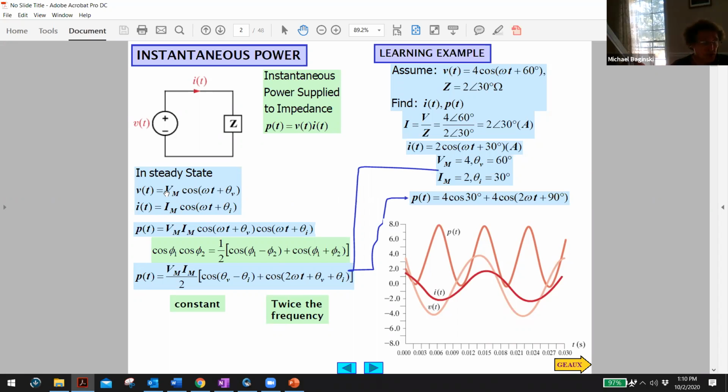All right, if I change this to a phasor, what would you do? You would say this would have a magnitude Vm, right? And it would be at the angle theta V, wouldn't you? You remember that? And if you change the current to a phasor, it would be magnitude Im at angle theta I, and you would suppress the omega t. The omega is only used to calculate the phasor impedances, the 1 over j omega C, right? And the j omega L. That's it. You got that?